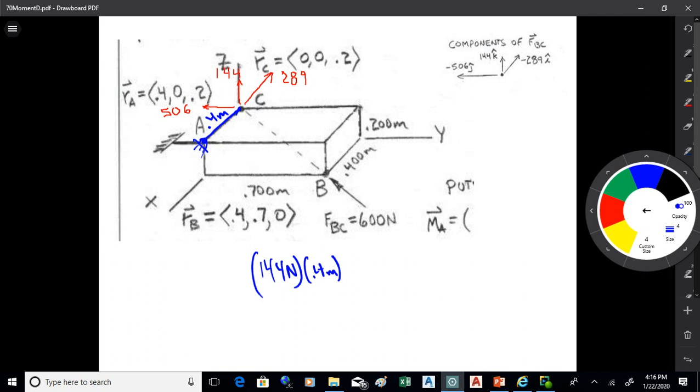What axis will it spin around? The distance is an x distance. The force is a z. So how will that rod spin if I apply that force to the rod? Yeah, it's going to come up, and boy, I didn't draw that quite right. It's tough for me to do this on a 2D piece of paper. Something like that. It's going to spin about a y-axis, isn't it? You okay with what I'm doing there? Seeing what's going to happen there? That's going to spin up and over A.